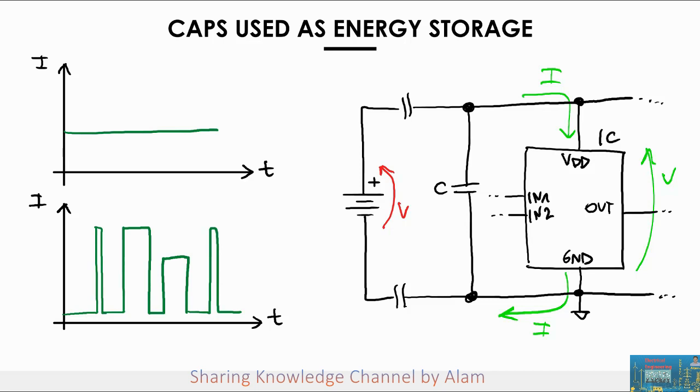So if you don't give them a little bit of order, nothing will get done. So you need to organize them and make sure that operations are executed in a timely manner. What happens is that the CPU usually has a pin where you have to apply a clock. A clock signal looks like this: a series of pulses, this is voltage, that keeps repeating themselves forever. They have a certain period, which is indicated with T, and the frequency, that is usually what is quoted for the CPU, is the inverse of the period.